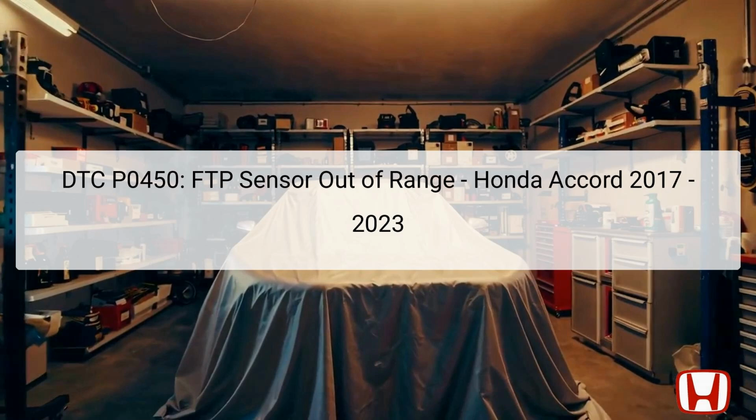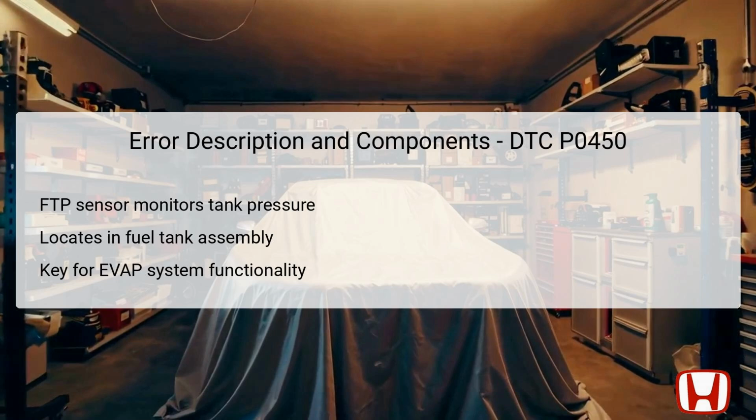the fault effectively. DTC P0450 indicates that the fuel tank pressure (FTP) sensor is out of its designated range. The FTP sensor is a crucial component located within the fuel tank assembly. Its primary function is to measure the pressure inside the fuel tank, providing vital input to the vehicle's engine control module, ECM, for managing fuel vapors and ensuring the proper operation of the Evaporative Emission Control System, EVAP. This system prevents the escape of fuel vapors into the atmosphere, reducing harmful emissions.